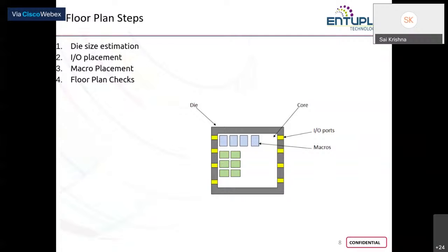The reason is that macros themselves are nothing but predefined designs. They have routing structures internally. So if you rotate it by 90 degrees, that means you are changing the direction of the polysilicon or any other metal, or for that matter every single layer inside that macro, which creates a problem during fabrication. That is why rotating macros is strictly prohibited, but you can flip them.